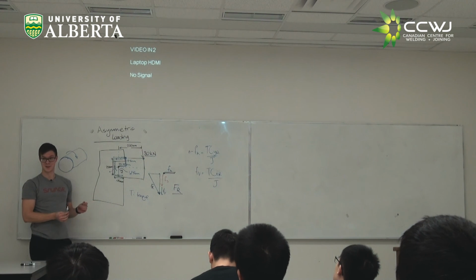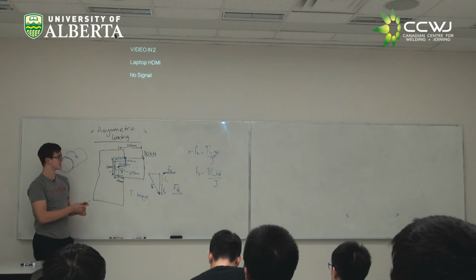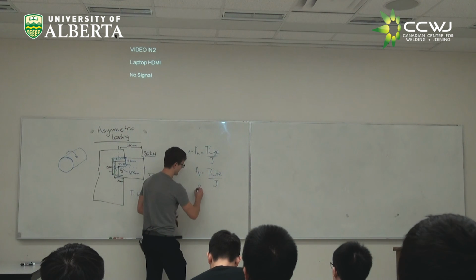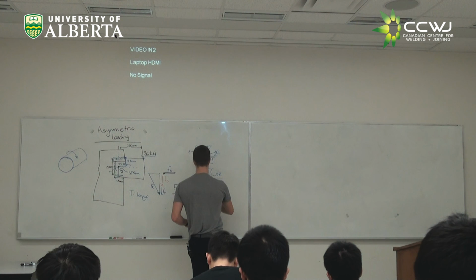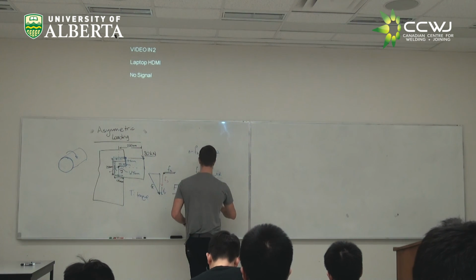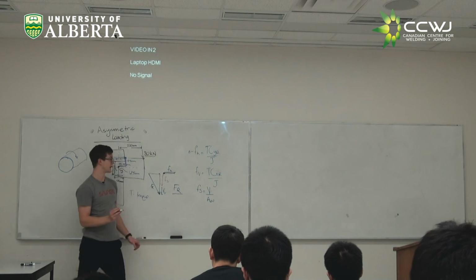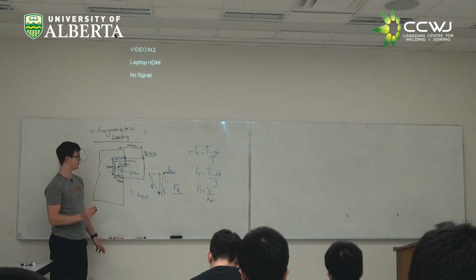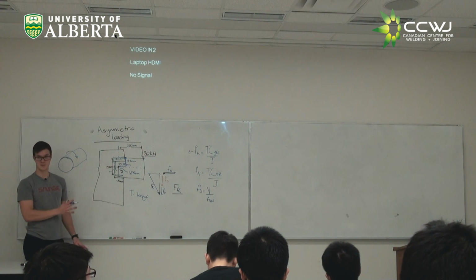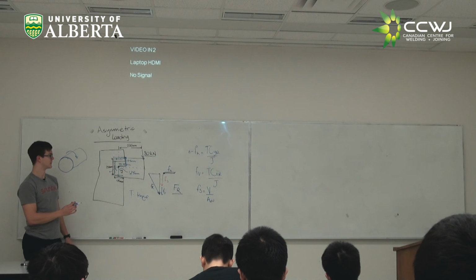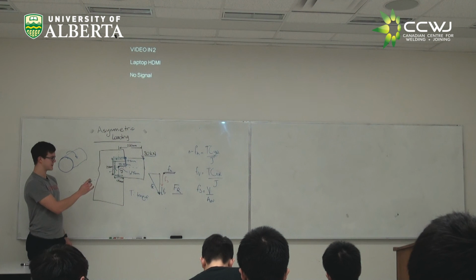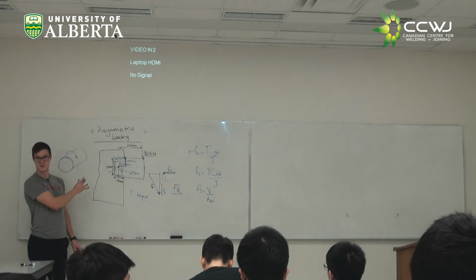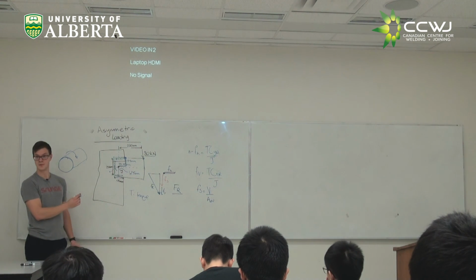It's not going to be 80 kilonewtons, okay, because in our case, we're given a formula for FS, which is going to be, I want to make sure I use this notation right, but I think it's V over AW. So we still actually have to calculate an effective, let me think about this for a second. We have to calculate what ends up being the effective length for our weld to get that V over AW.